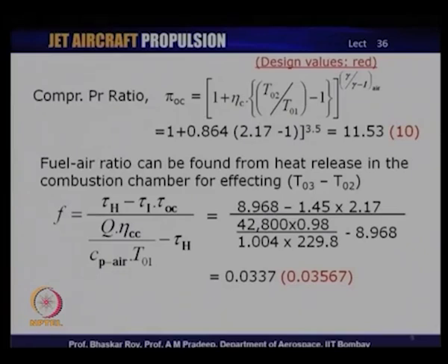Now, this is not totally unexpected, because if you remember the compressor map, it has a design point, but the compression ratio is not maximum at the design point. There is a region of the compressor map in which the compression ratio is indeed higher than the design point, and of course, it moves towards the stall. So, this particular operating point is now somewhere between the design point and the stall point, as a result of which it is working at a higher compression ratio than the design point, and hence some of its performances would be accordingly altered from the design point quite substantially.